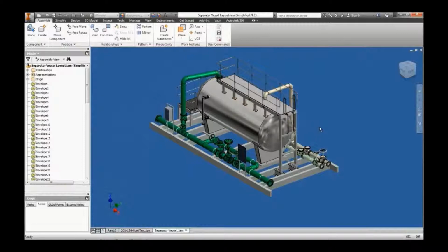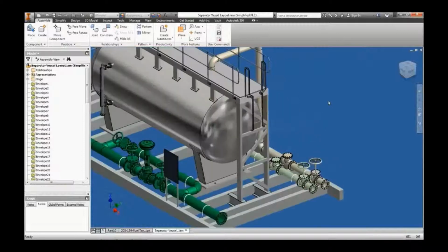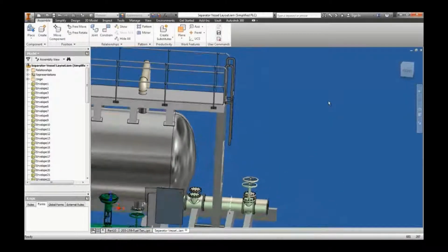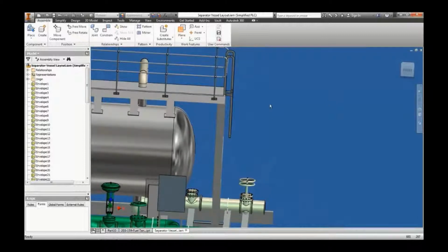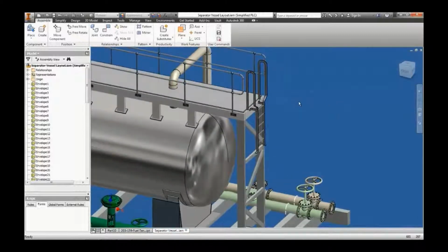Now this is a generic ladder as far as we're concerned within our company. It's just, in this case, about a metre long. It's obviously not big enough, it needs to be longer. Rather than designing the ladder from scratch every time, we can use a standard ladder, and we can put a bit of iLogic code in there.